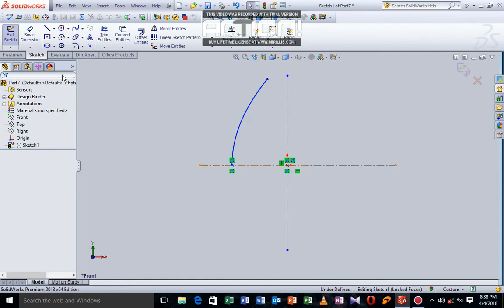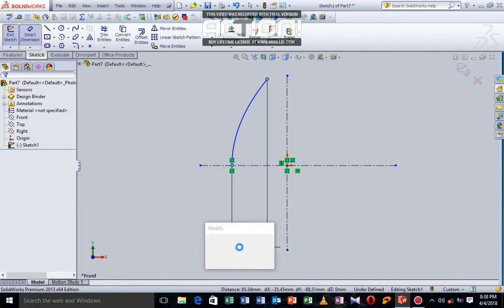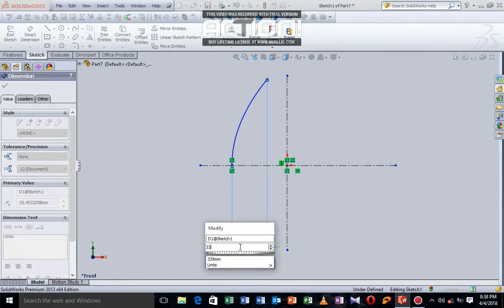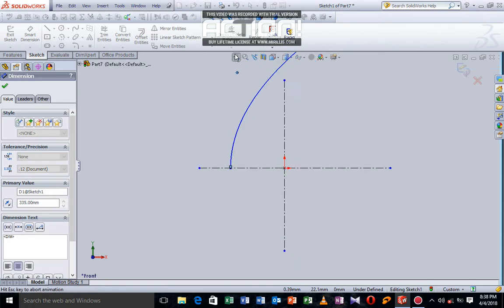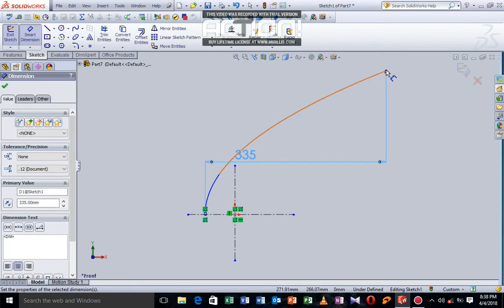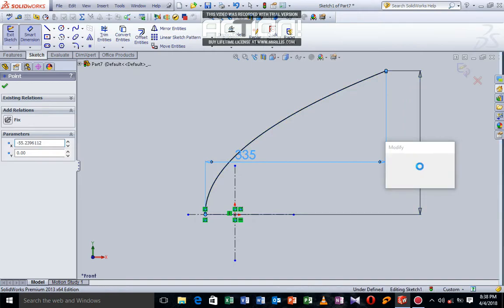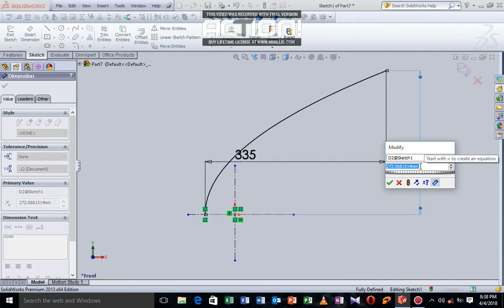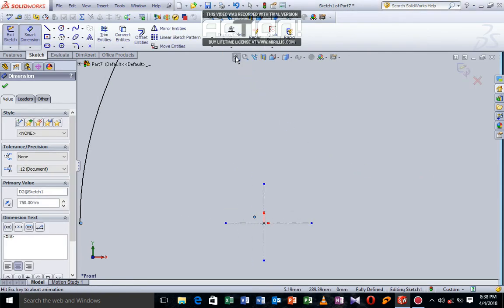So starting here, you're going to go over here. So go to sharp, and you're going to go here. We'll go here, and we'll go down, and we're going to call this 335 millimeter. So it knows the unit already, so we're going to reduce it, and we're going to name this distance from here to here. We are going to name this distance 750 millimeters.